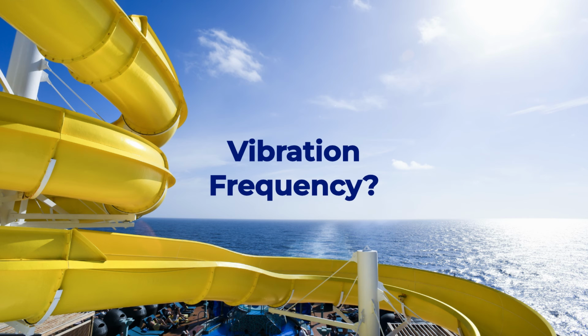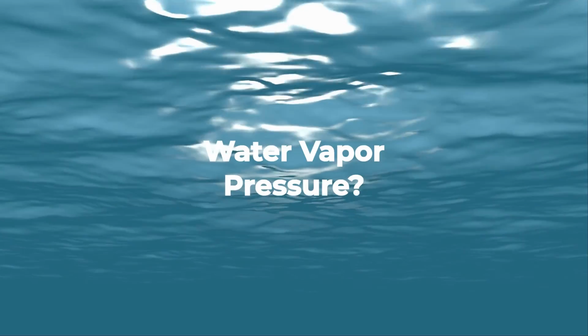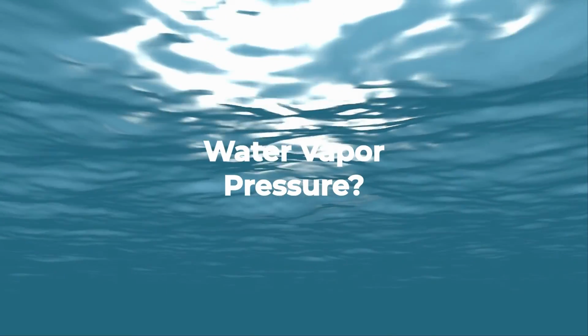Same with the vortex meter, and we're just counting the vortex formation. Again, it's a low pressure area. It's causing the bar to stress from one side to the other, and we're just counting the pulses. Every time a vortex is formed, we're getting a pulse out of the shedder bar, and each pulse is proportional to the flow.